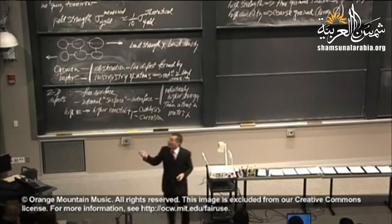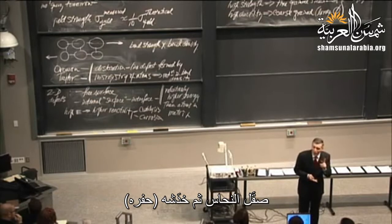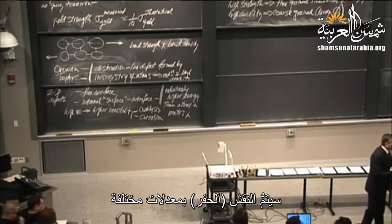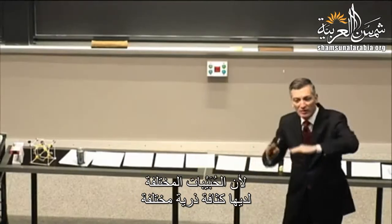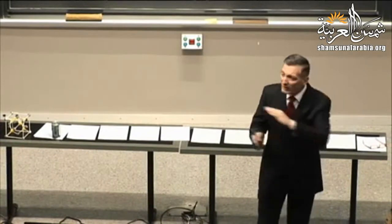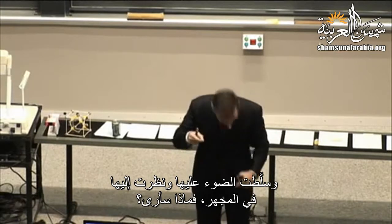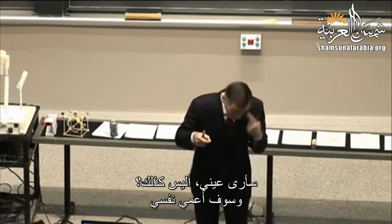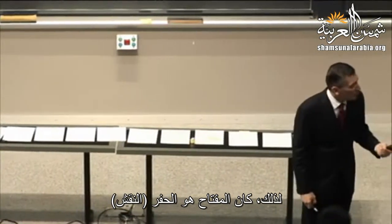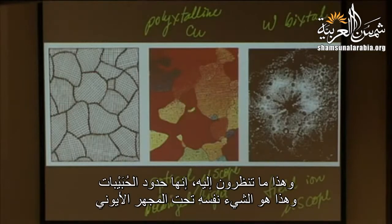All right, so what did he do? He polished the copper and then he etched it. And what happens with an acid etch? It will etch at different rates because the different grains have different atom densities. If I take a piece of metal and polish it super bright, and then shine a light on it and look at it in a microscope, what am I going to see? I'm going to see my eyeball, right? I'll blind myself. So the key was to etch. And then when you etch, you differentiate the different grains. So that's what you're looking at, the grain boundaries.